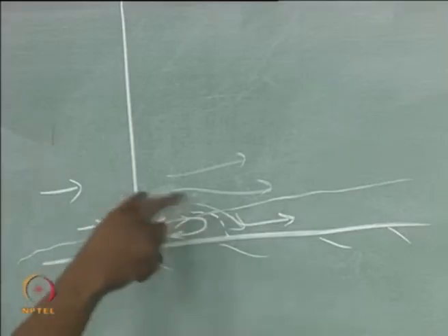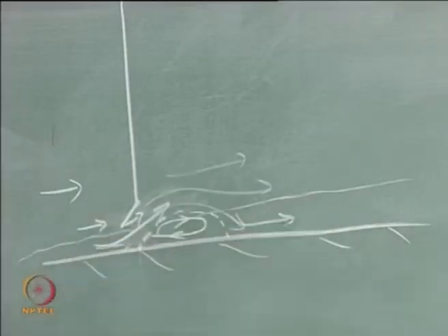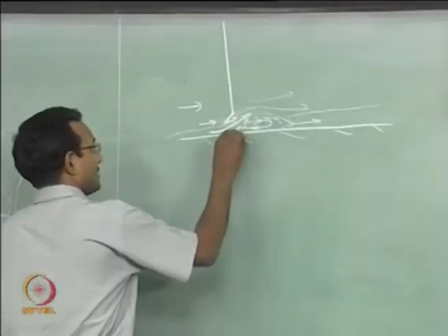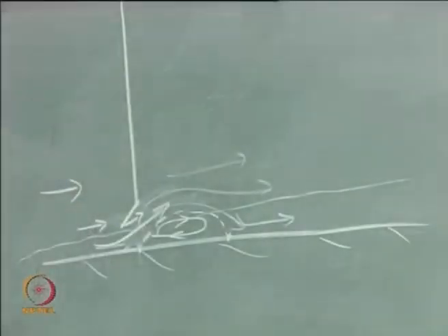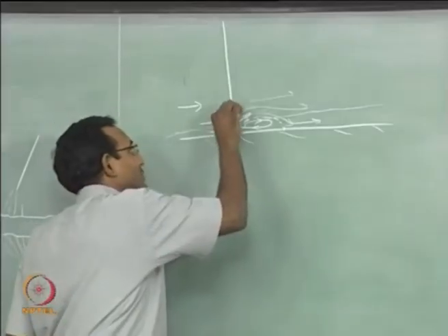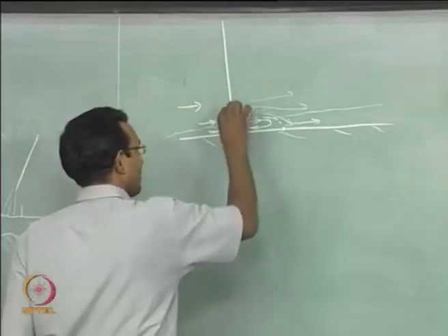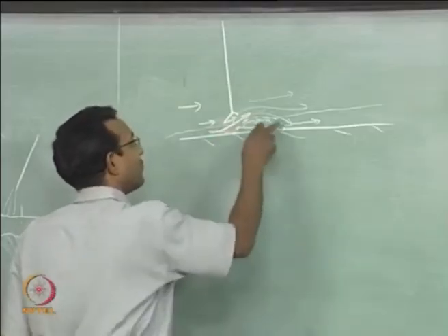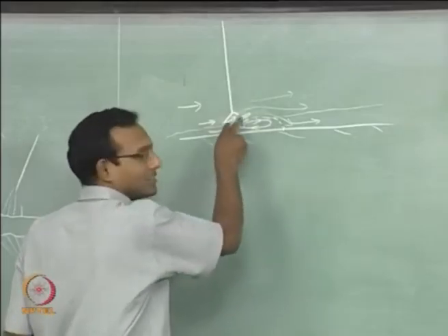That dotted line is the one streamline which is separating the fluid that is circulating and the fluid that is moving. That's your stagnation point here and here, separation stagnation points. Okay. That's too much aerodynamics probably for you right now. But what happens at this corner is there will be a small shocklet here. We won't worry about why it has formed right now. And after that the flow field is again supersonic flow or subsonic flow depending on the conditions here.